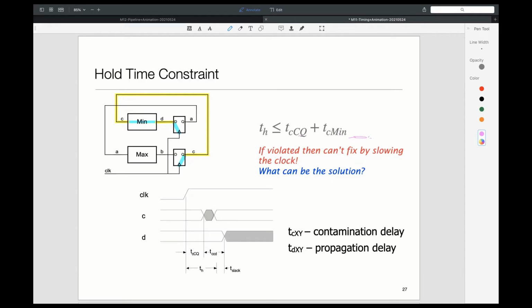So there are a couple of options. Maybe I can slow down the min delay even more by using a less efficient design. Like, let's say it's turning out that the problem was occurring because I was smart and picked some fancy carry look ahead adder or something like that. Maybe I'll replace it with a carry ripple adder or something. Let's use a slower design, right? So I could do that, or artificially add gates. Maybe if I'm running into a problem, I can add some even number of inverters out here, right? I can slow things down to do it.